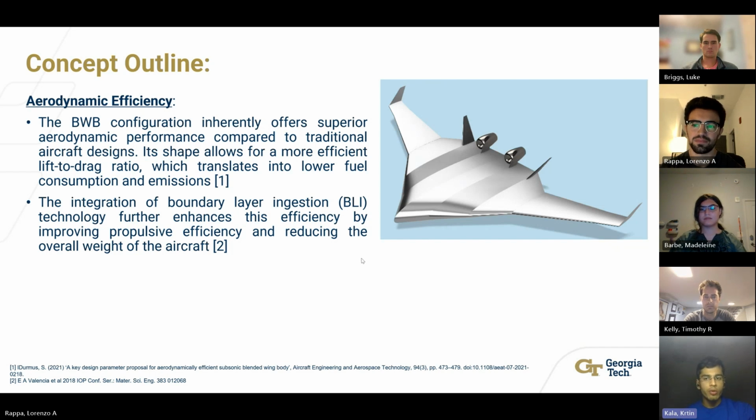The Jet Zero blended wing body aircraft offers an unprecedented aerodynamic efficiency, wherein the entire body of the plane works as a lift generating device. This is due to the seamless integration of the wings and the body, which was not seen in the conventional aircraft design models. This reduces the fuel consumption, and additionally, we have integrated boundary layer ingestion technology. This minimizes the drag by reusing the airflow that would have otherwise created turbulence.